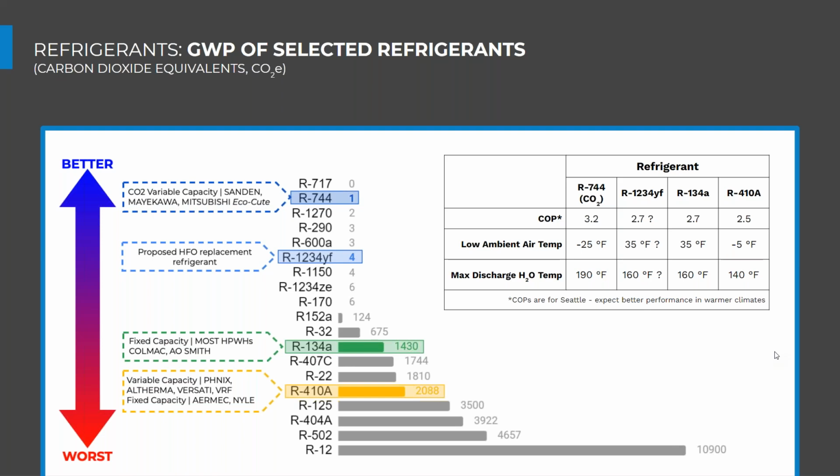And then these are two heat capacity charts, one for an HPA15, that's an R134A heat pump water heater. And we see that it drops significantly with air temperature. Our entering air temperature is down here.